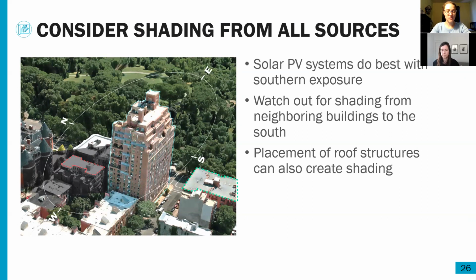And so it's especially important for buildings to have exposure to the south. So this building that is outlined in red here is just to the north of the taller tower. That I wouldn't recommend for solar at all. It's just never going to be a financially viable system. However, the building just to the south of it is the same distance from the tower, but it's south of the tower, and so it would be completely fine. It's an ideal candidate for solar.